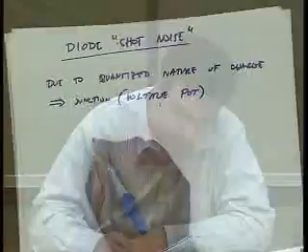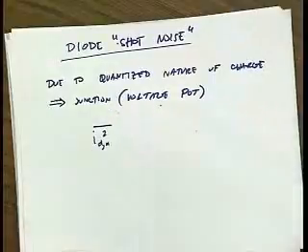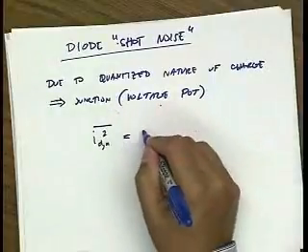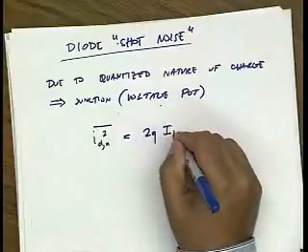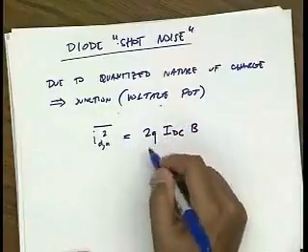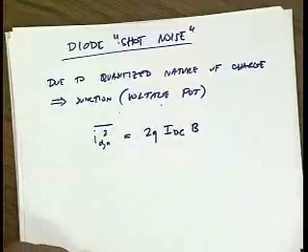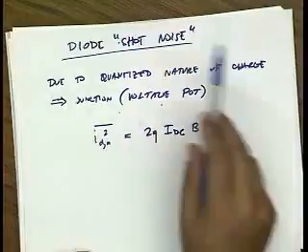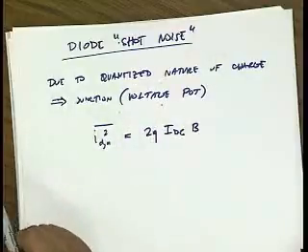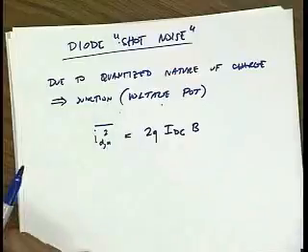And if you do the statistics, you find that the noisy component of this current is actually proportional to the DC current, the bandwidth, and the quantum charge, right? Basically, the amount of charge that you carry. So you could think of shot noise as just being due to the lumpiness of charge. Okay. Now, there's a nice analogy for shot noise.